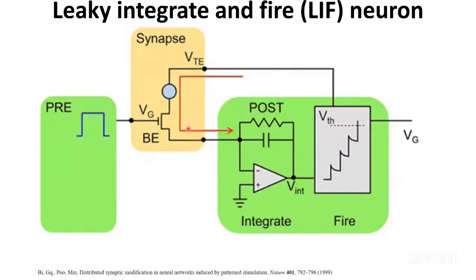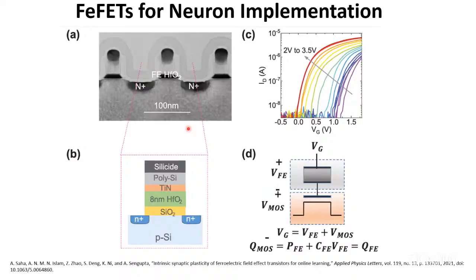First, let's discuss the implementation of the neuron using ferroelectric FETs. And what a ferroelectric FET is, is also important to understand. If you see here, this is the figure of a ferroelectric FET. What we are doing essentially is changing the gate stack and incorporating a ferroelectric layer in between, which is the HfO2 layer, or hafnium zirconium oxide layer. This is the doped HfO2 layer, which is doped with zirconium or silicon.